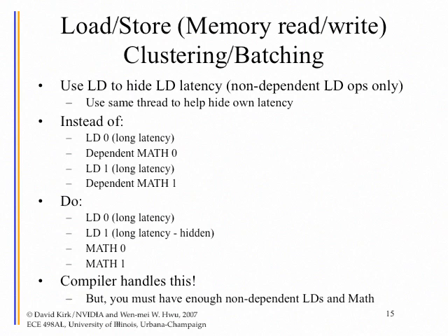However, as we explained before, you will have lots and lots of these warps in each one. If each warp is capable of tolerating, let's say, 4 more cycles of memory latency, you can end up needing a much smaller number of warps. That's a very useful situation when the warps or the threads use up so many resources, such as registers, that you cannot fit more warps into these SMs.